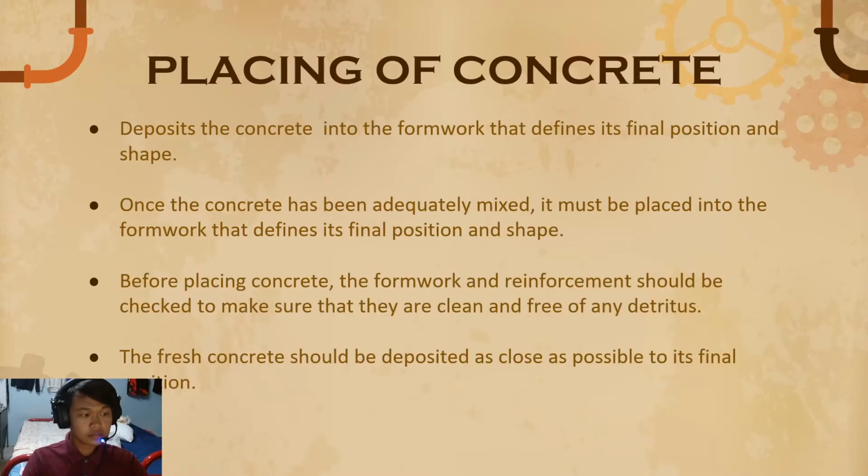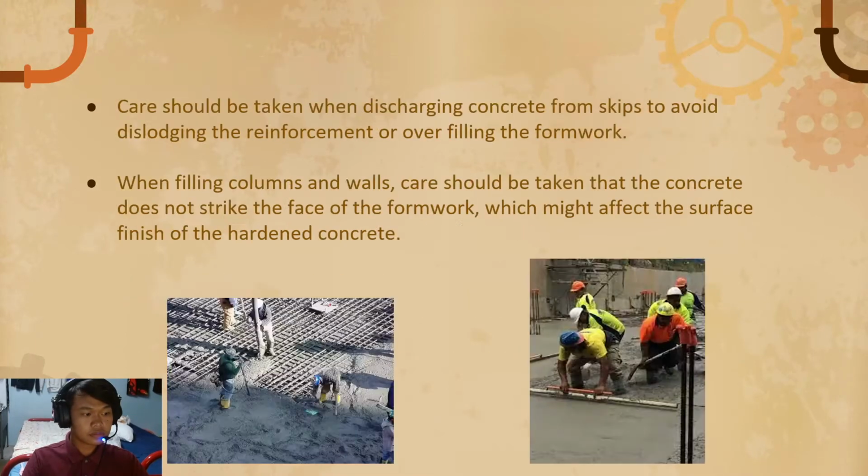Point 6, when filling columns and walls, care should be taken that the concrete does not strike the face of the formwork, which might affect the surface finish of the hardened concrete.